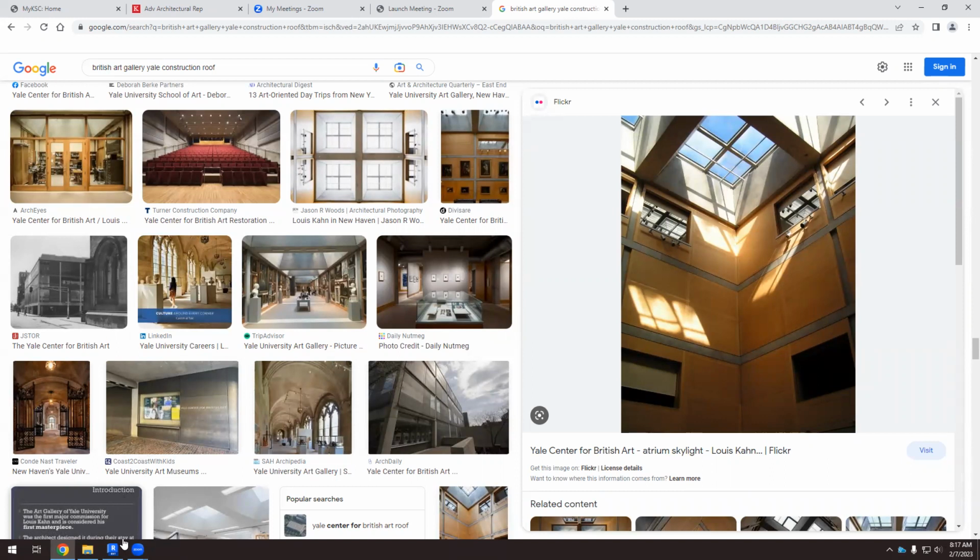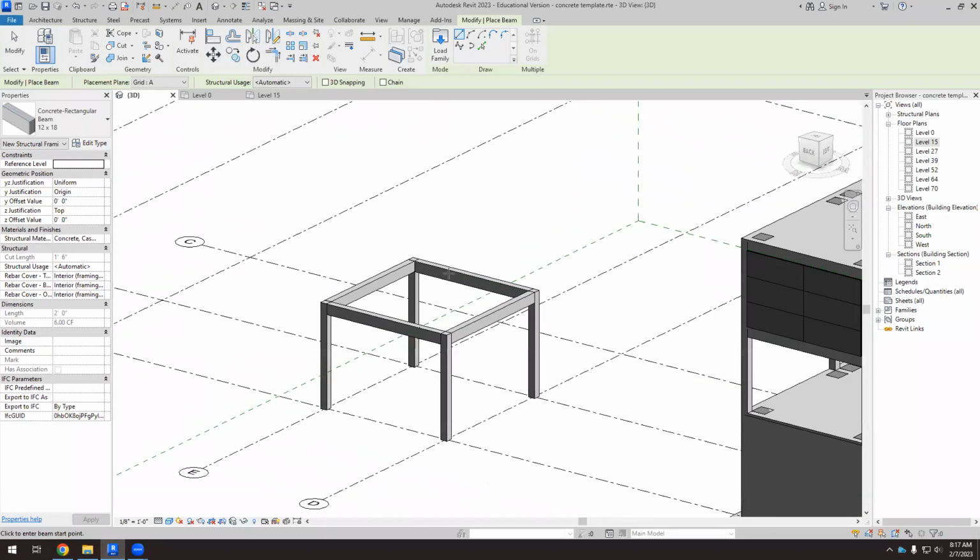We're going to use a component model in place, and then we are going to use extrusion and then subtract, or we are going to use the component model in place but with the sweep option. So we will create a shape, and then we will rotate that shape with a path, and then we will create that option. So there are 2 different ways to do that. Let's try both, and then you can decide the one that you like the most.